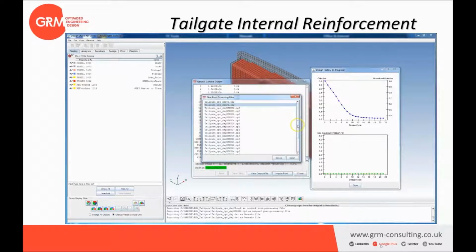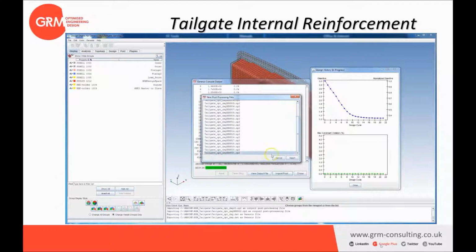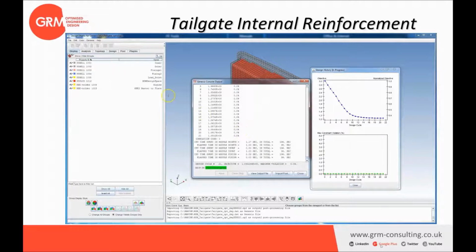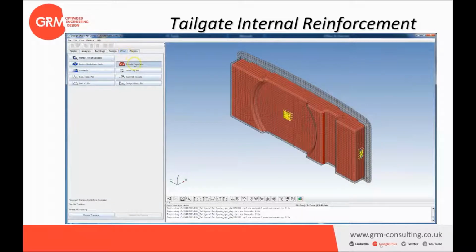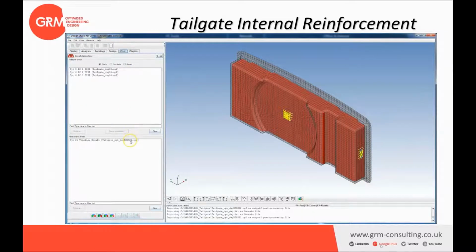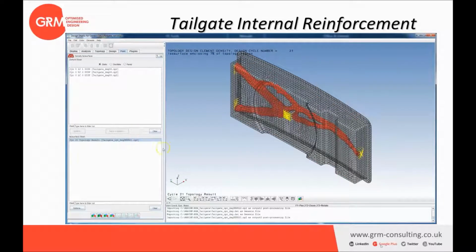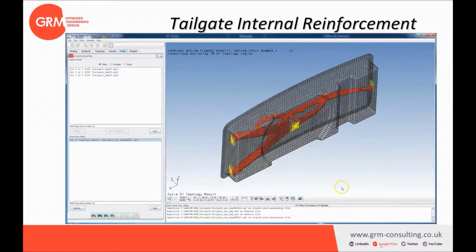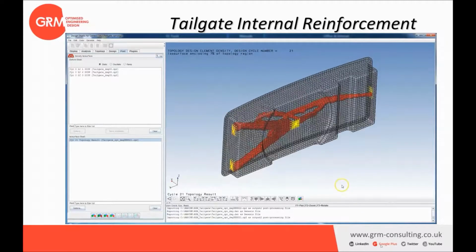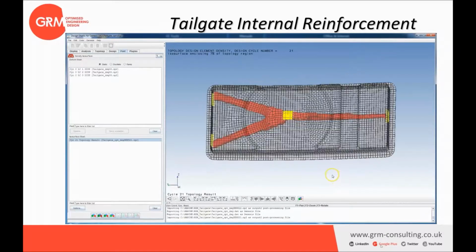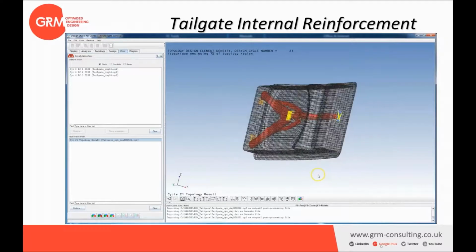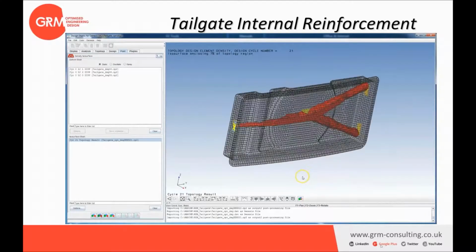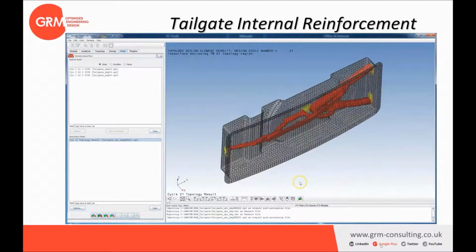In this example, we run the optimization locally, but it will work as well if you run it on a cluster. And we can check the RDM results. That's it, as simple as that. So we clearly identified the load path for this 3 load case, where the material is, where the load is going from one pad to another.